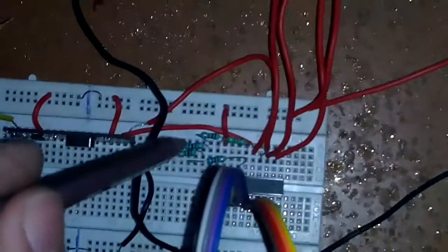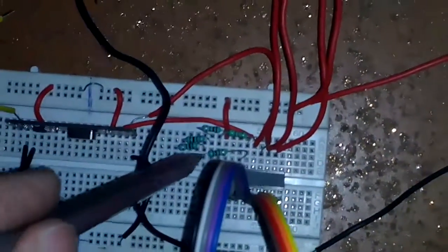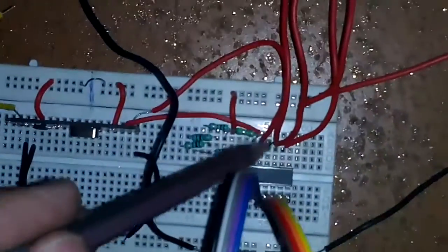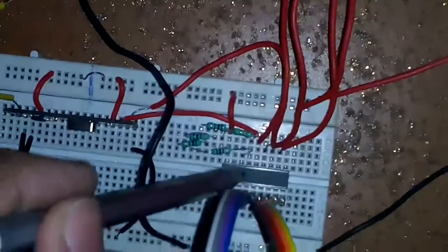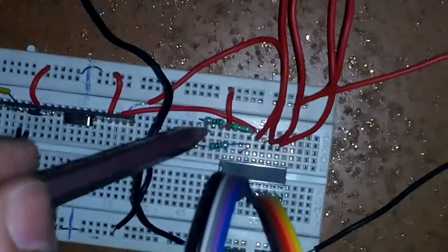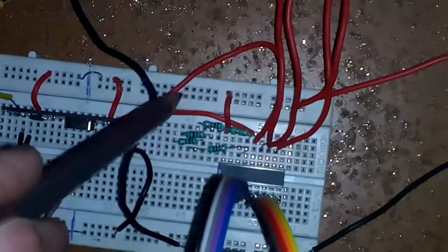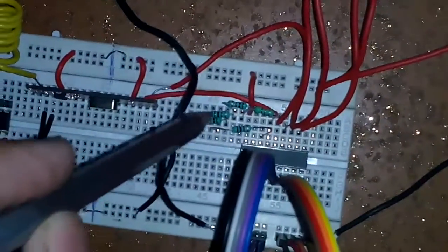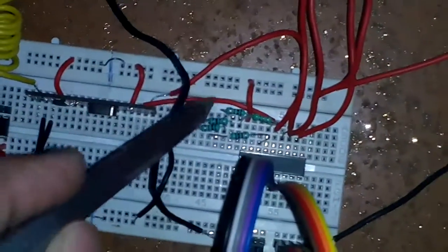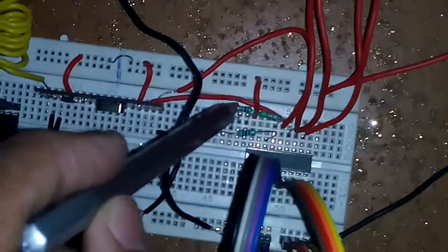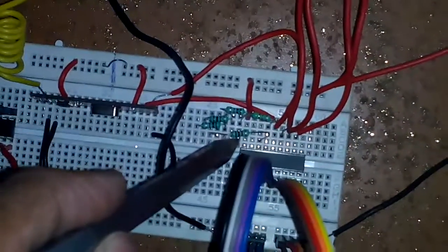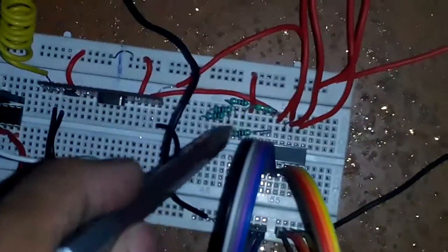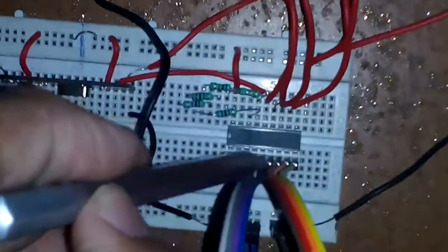And here are 4 resistors, as we require a 51 kilo ohm resistor for the transmission and receiving. One is a 47k resistor, and the others are 1k each. So 1k, 1k, 1k, 1k and 47k give us 51 kilo ohm, which we require for the transmission purpose.